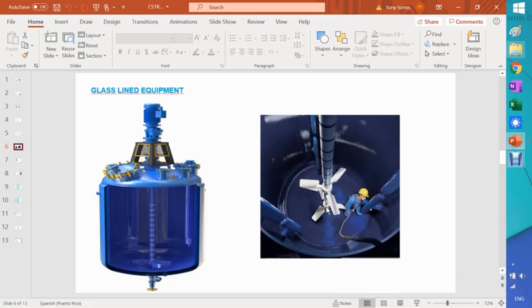So again, that's what we call tag out, lockout. You close the switch for this guy, you put a lock on it, and this guy might even have the key for that lock, so nobody can use any key to open up the magnetic switch where the starter for this agitator is located. Okay, that's another story. I'm just talking a little bit about safety.